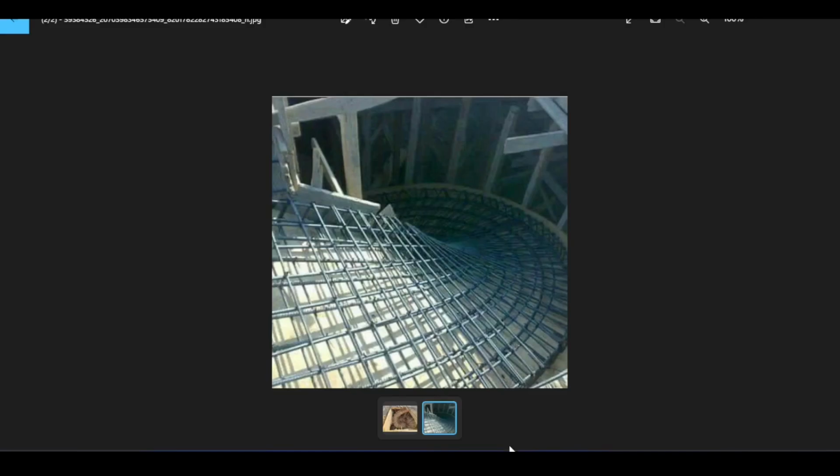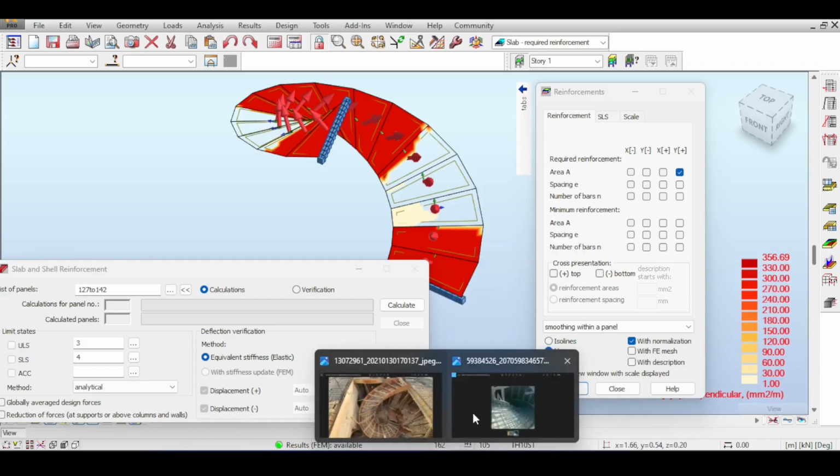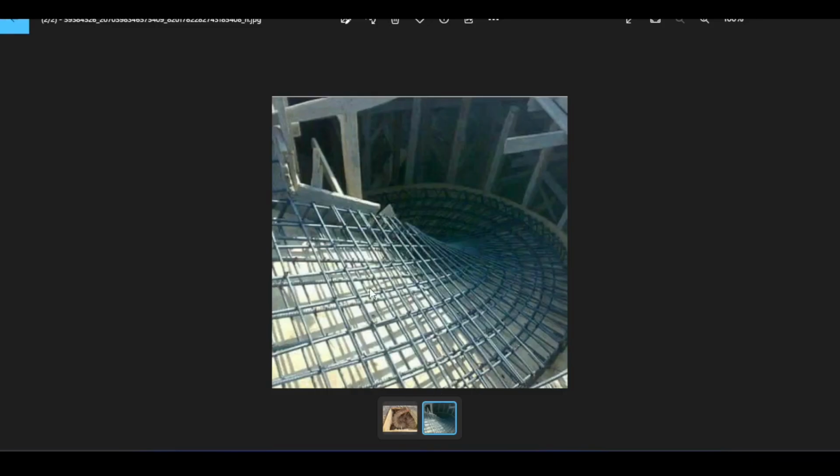So for this, I said the minimum is 1 phi 10 each 20 centimeters. Personally, if I am the one doing it, I would say 1 phi 12 each 20 centimeters, top and bottom, longitudinal and transverse. So in both directions on both faces. And the lateral direction is something I would stir up, or try to box together like this, to have one sturdy reinforced concrete staircase, because it's under torsion, and I'm usually a little bit worried when I see torsion.